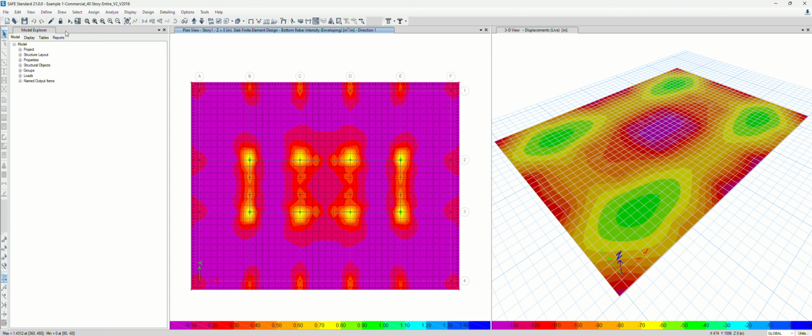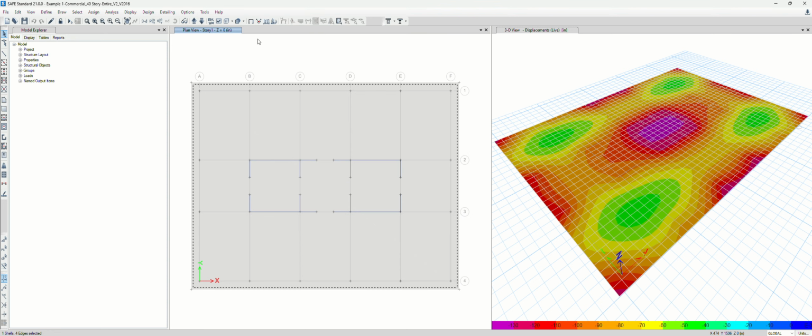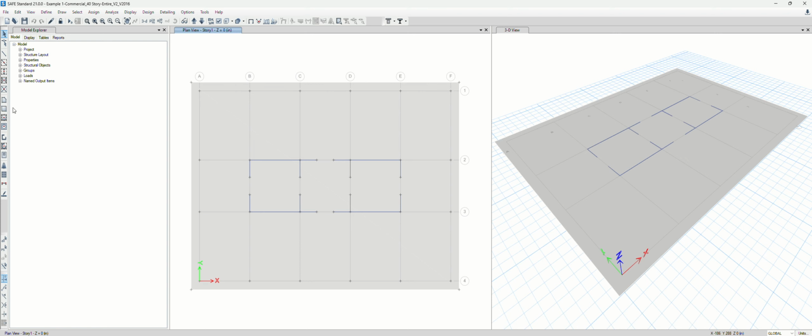So I'm gonna show you how to define the design strip, and then show you how to collect the strip forces in shear and moment, so it's visually more understandable. You're supposed to have taken some class about two-way slab design. In ACI 318, we have the equivalent frame method, which is pretty much similar. So what we're gonna do here, we're gonna click design.